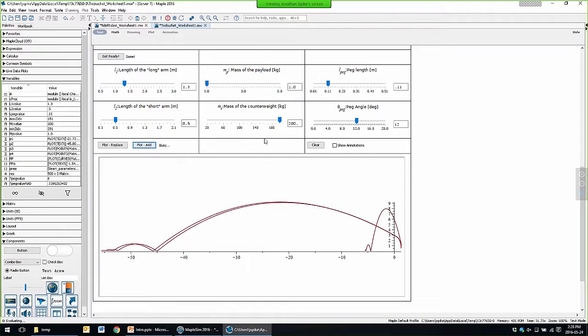And we'll just take a look at a couple more values here. So for instance, if we go up to 12 degrees, we barely see anything. I'll just skip up to even our maximum on our scale here. And our maximum now actually is going to result in an angle that has a little bit less height than our other values. We can see here, and a little bit less distance. So this already shows us that our sweet spot is possibly between 8 and 16 degrees, somewhere in there. Maybe even including 4 with this configuration that we have here.